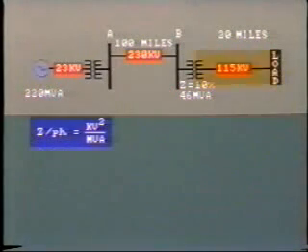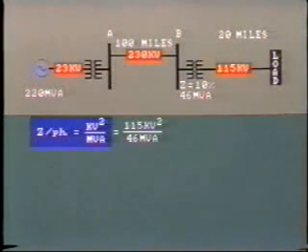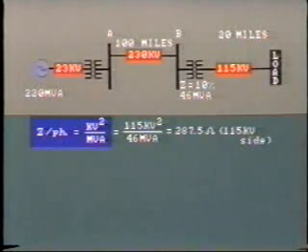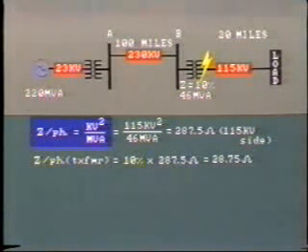Using this expression, we can calculate the impedance of the load, including line impedance, being fed by the 46 MVA transformer. The ohmic impedance of the circuit under rated load equals 115 kV squared divided by 46 MVA, equals 287.5 ohms. The nameplate informs us that the short circuit internal impedance of the transformer is 10% of the rated circuit impedance. So if a three-phase fault occurs at the transformer terminals, the impedance will fall to 10% of that 287.5, that is 28.75 ohms. This is the internal impedance per phase of the transformer.